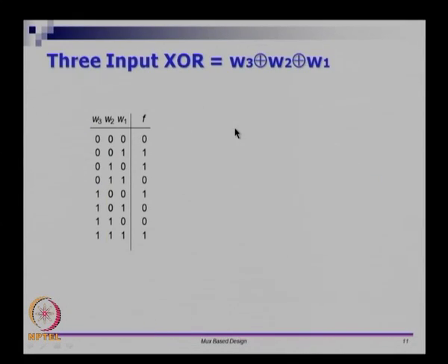So, now I am going to take you through a few other examples. At this point I want you to acquire one basic skill that is needed for you to do a lot of logic design. If you are given a K-map of 2 inputs, you should be able to recognize immediately whether the truth table given is for AND or XOR and XNOR.